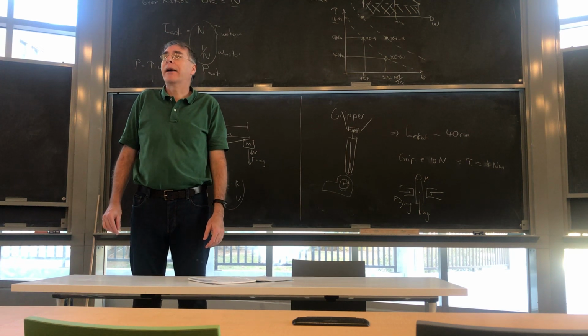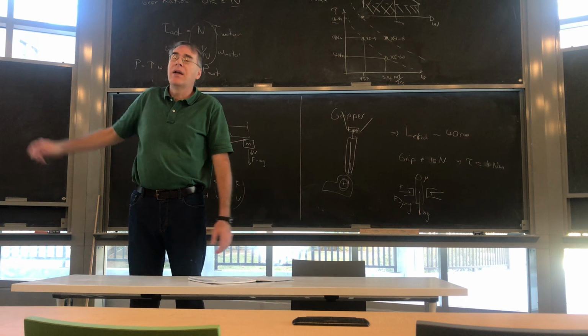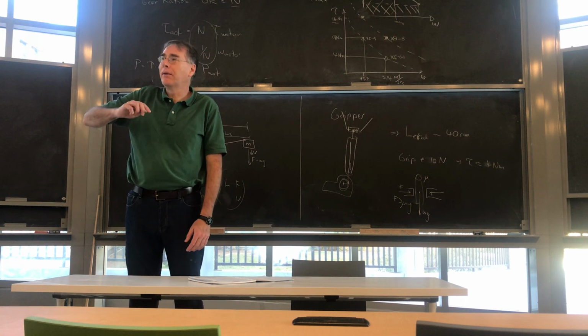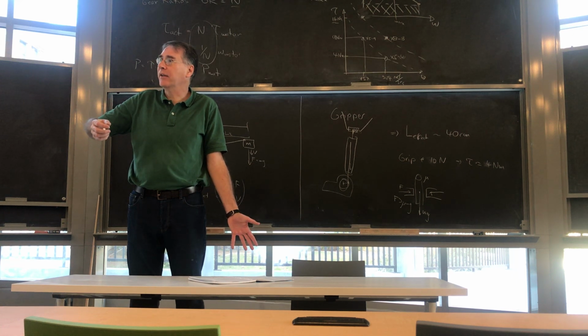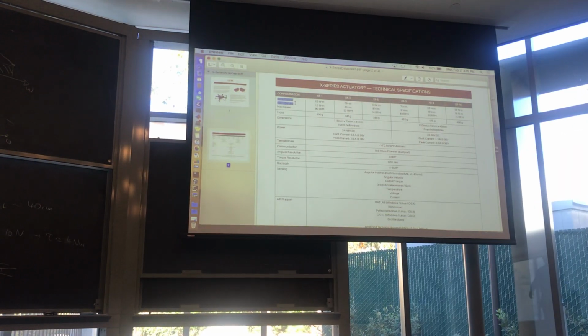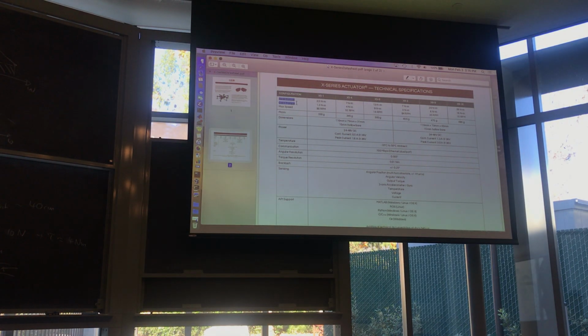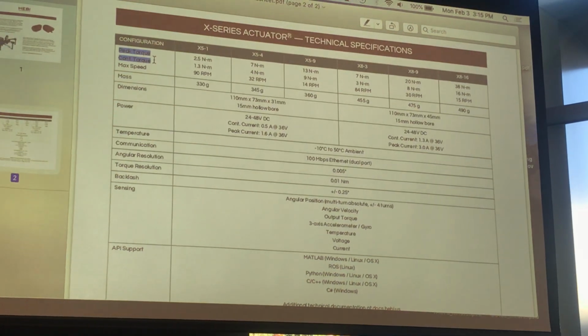My comment is, if you want to hold a weight out there, you can't rely on the peak. If you want to hold the weight and then move it, that motion is probably only going to be a fraction of a second or half a second. So you can probably use that peak to give you a burst of acceleration temporarily. In these calculations, I tend not to worry so much about how quickly you're accelerating unless you're going completely nuts, like maybe our air hockey team.